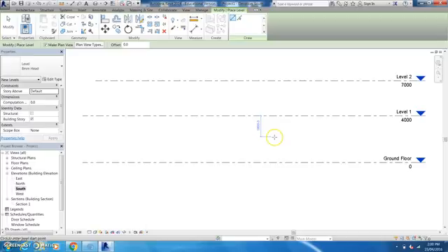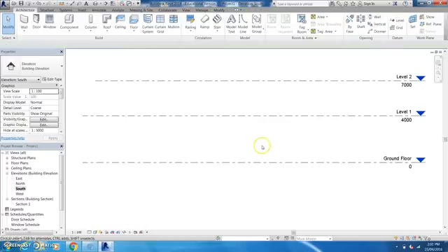Now I'm going to go ahead and change some of the sizes on this. So first of all, I'm going to come to the ground floor, 0. Now, as I said, guys, I'm just starting off quite simply here. If we wanted to draw our house on piers or foundations, we can put another level along here at a negative value.